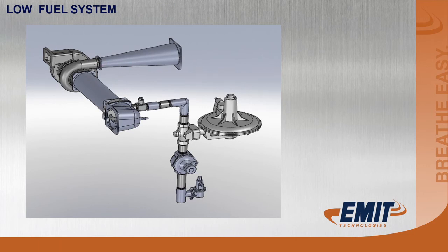Low pressure fuel system works quite a bit different. In a low pressure fuel system, we're blowing the boost directly into the engine, but the gas is being mixed on the low pressure side of the turbo. So this is going to go into a negative inches of water column.